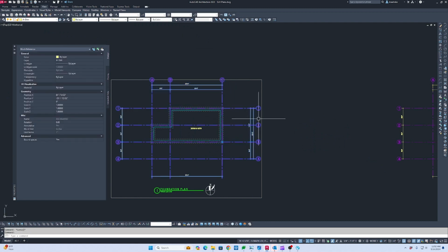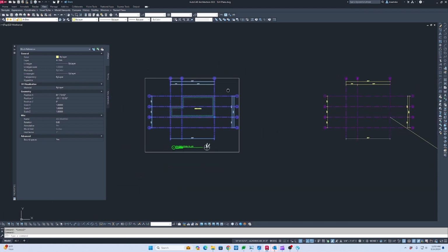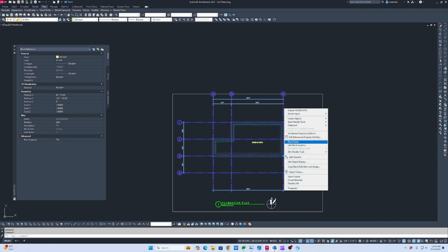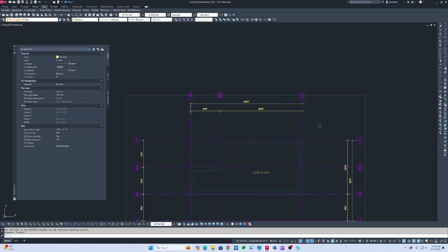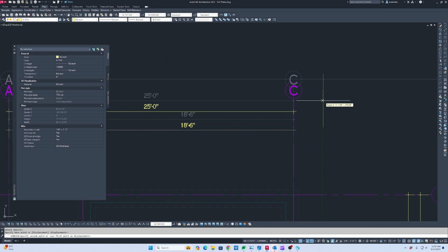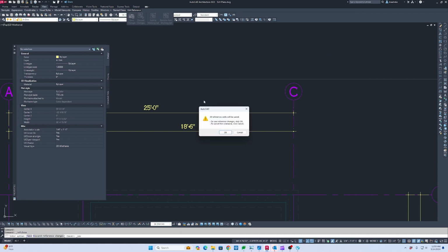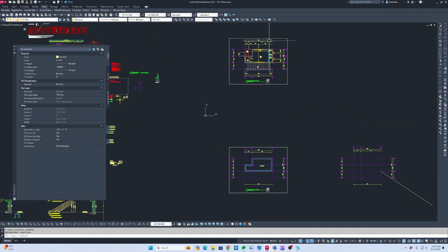So now that that is there, look at that. I'm a little too high for my printouts. Yeah. Let's just move these down. I'm going to do, again, if you remember, we can edit in place. Yes, that's the one. And then this can just slide down to fit. Remember, I made that white line to be where my viewport is set up, so that I know that if I'm outside of that white line, I'm outside of my viewport that I have set up. So it's an easy, quick way to check without having to go back.